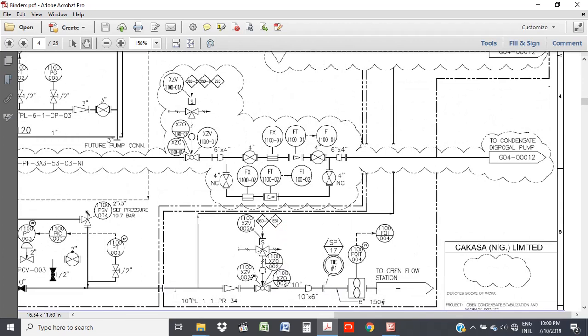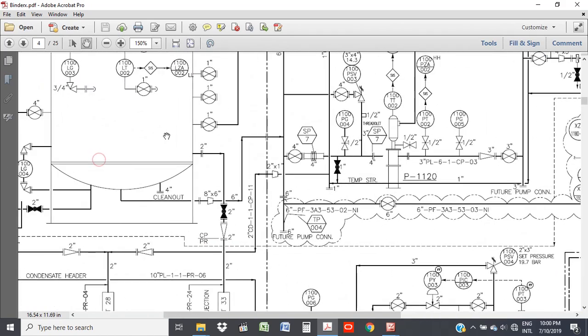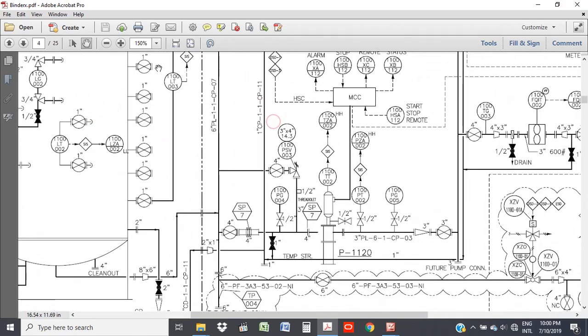So this would automatically pick up a signal. It would normally be connected to the fire and gas detection system, and once it picks it up, it would automatically start closing. A lot of times they close an inch per second. So depending on the size of the valve, if it's a 10-inch valve, in 10 seconds it should normally close and stop all flow to this, which would help in putting out the fire. So you have them all across major equipment because you want to protect those major equipment.